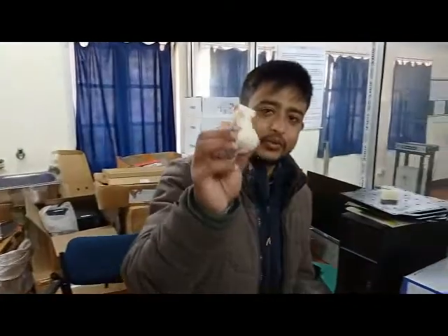We'll select some temperature, we'll heat the tank. The tank is filled with 40 liters of water, and the water is mixed with some soap, fine. So those soap along with water, and we'll just heat it up to 70 to 80 degrees centigrade, and drop this and put it for around 3 to 4 hours depending on the shape. So since it's a simple shape and very small in size, the time required is very less. If we have a very complex shape, I will just show you. We have one complex shape there, so it took around 2 to 3 days to remove the support, fine. So now we'll just move to the tank and see how we remove the support part.